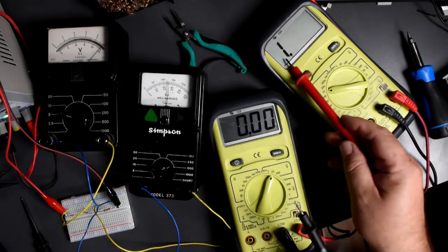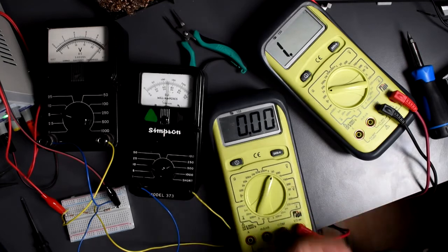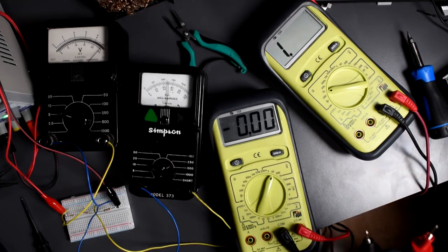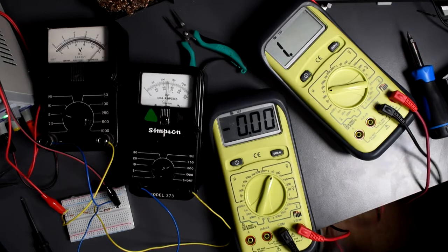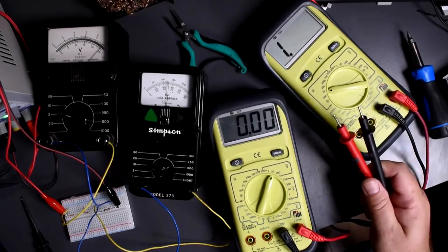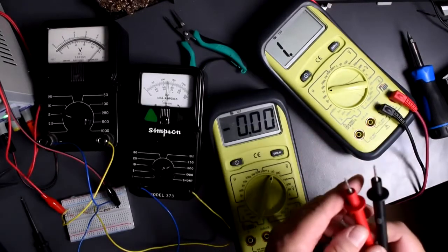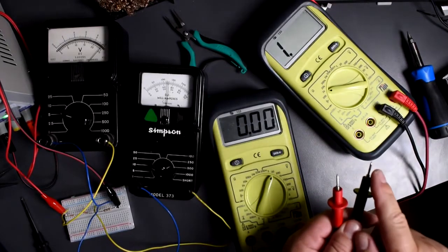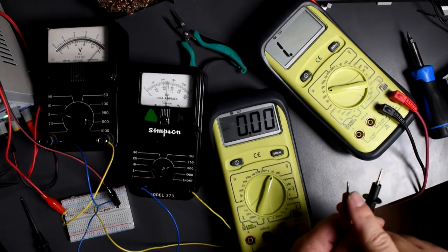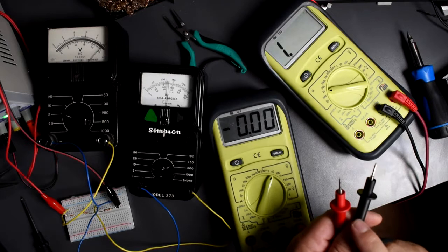So it's correct, the display shows correct. We're having much greater resistance than 2 kilo ohms across the probes. Now, how does the ohm meter measure resistance? It is going to introduce a tiny bit of voltage across the probes, across the tips, and which is going to make the current flow from one probe through the resistor to the other probe.